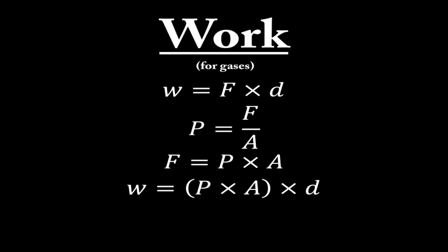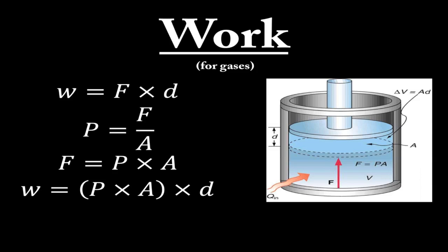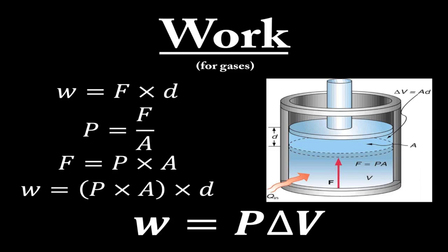You may be wondering, what is this work we're talking about? The formal definition for work is force being displaced over a distance, but for our purposes, work is performed on or by gases. We can rewrite our work equation by understanding that gases are compressible, expandable. So using the pressure formula of force displaced over an area, we can rewrite force and substitute that into our work equation. Our grand work equation would be pressure times the change of volume.